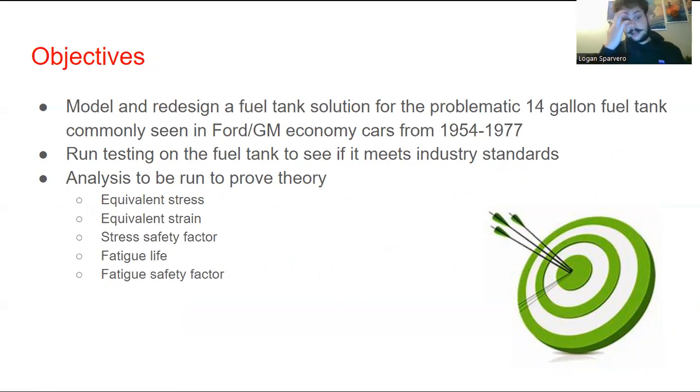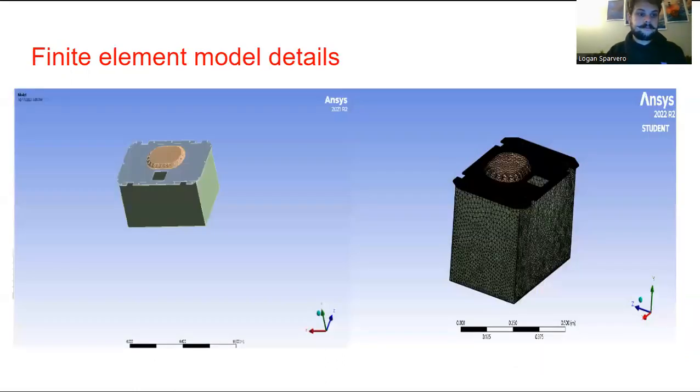The analyses are equivalent stress, equivalent strain, stress safety factor, fatigue life, and fatigue safety factor. Fatigue life will give us the number of cycles it can withstand. Stress and strain is the impact force it can withstand. The stress safety factor and the fatigue safety factor are its reliability. So there's a lot of things we're going to be touching on.